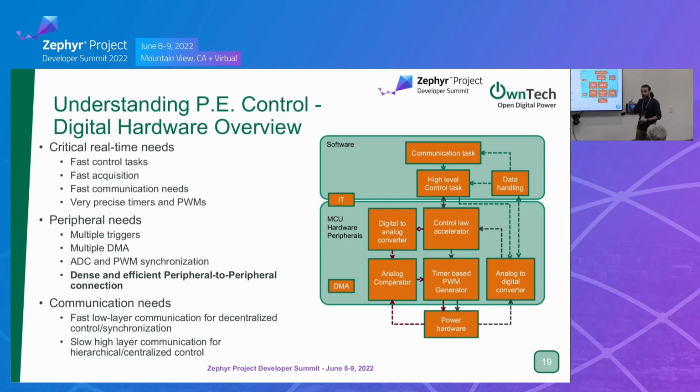That's true. Some digital power SoCs, they actually integrate this. You can hardwire your measurements to some of the leads and code that into your microcontroller so that it is a hardware check. And if the check goes beyond a certain threshold, it cuts the power. So that kind of stuff is integrated in new digital SoCs. It is a feature that we can see emerging in digital SoCs today, indeed. Okay. Even if you're not doing current control, if you're doing voltage control, you can still implement that kind of safety feature and it works.